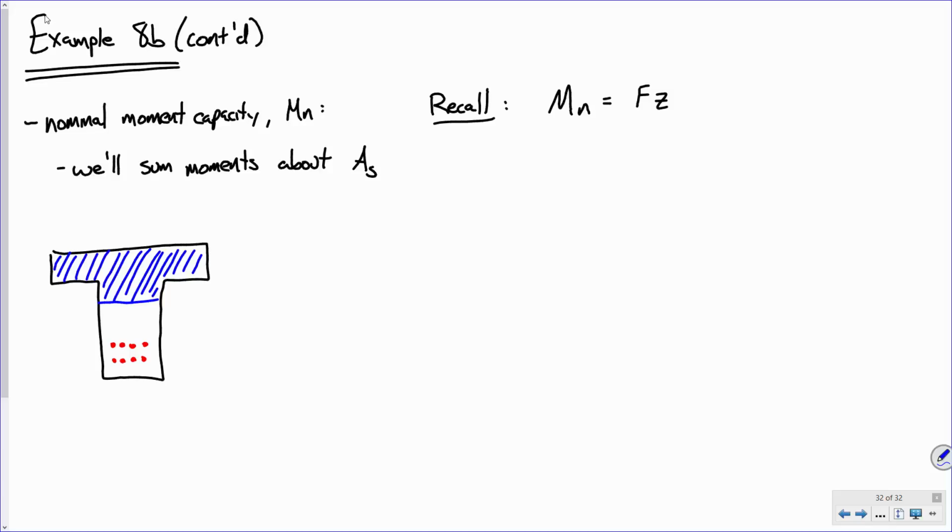And this stress block is proportioned such that the area of this stress block will generate the same compressive force as this steel reinforcement will, right? I'm going to split this up into 2 different beams. I'm going to say that this equals the following beam.